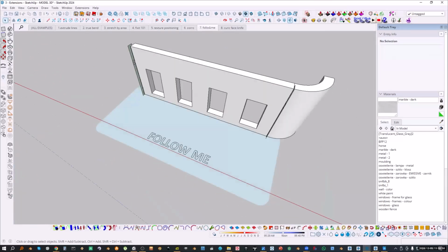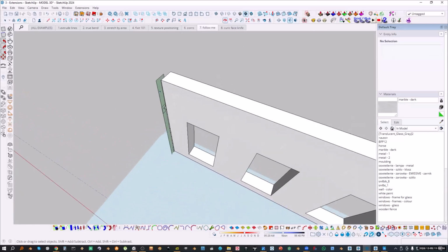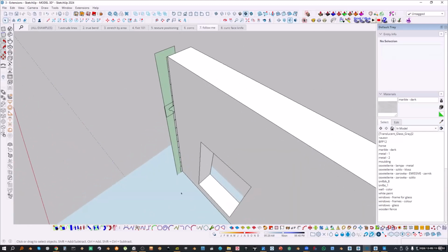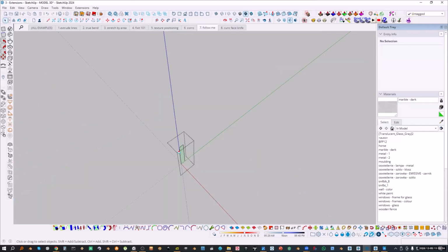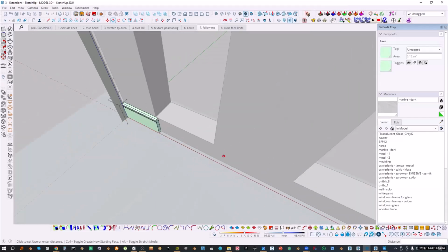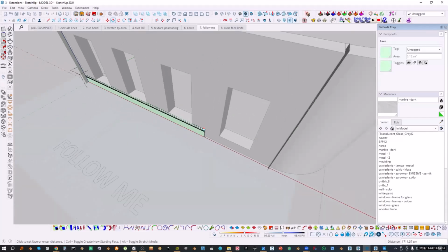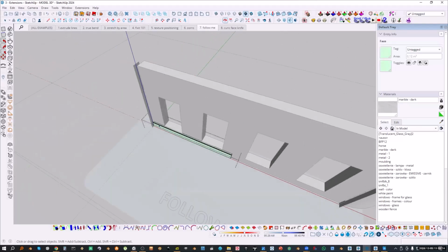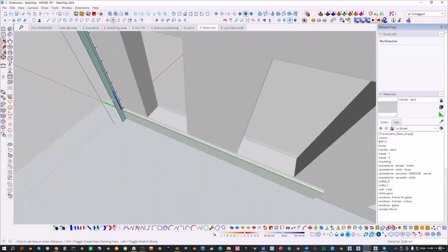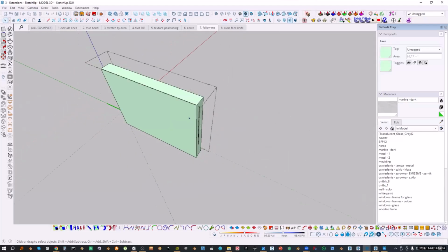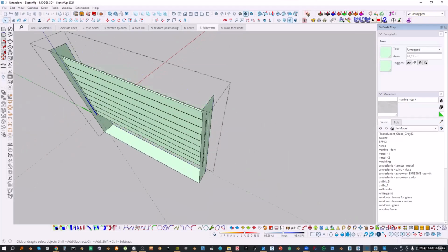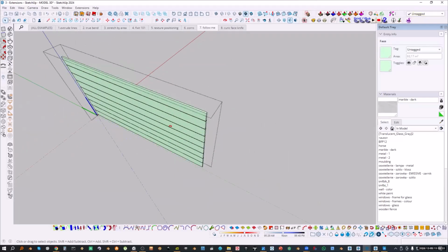So on to the next one, Follow Me tool. It's not really problematic in this place because you don't really need Follow Me on long distances or even short distances, but straight lines, basically straight movement. You don't need that. You can do it very quickly with just push-pull, and you can then group and delete the rest.